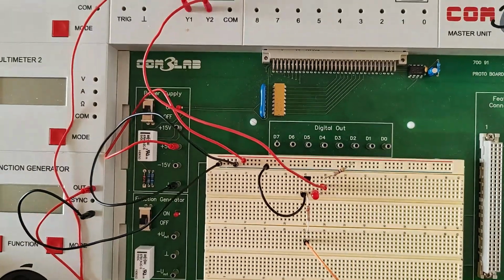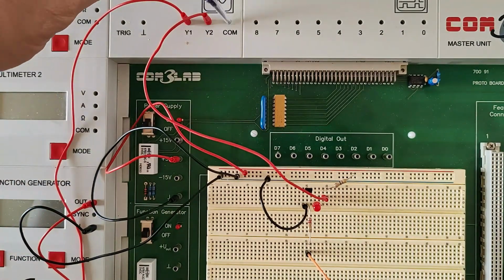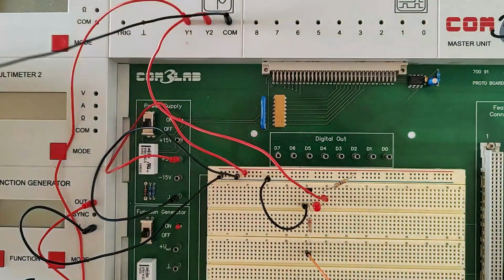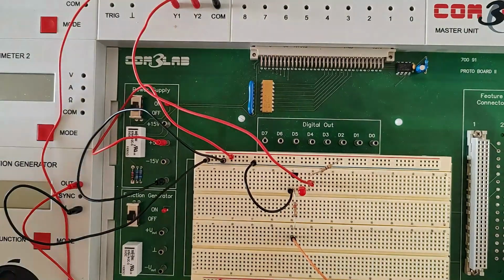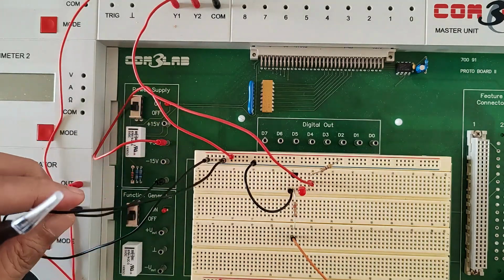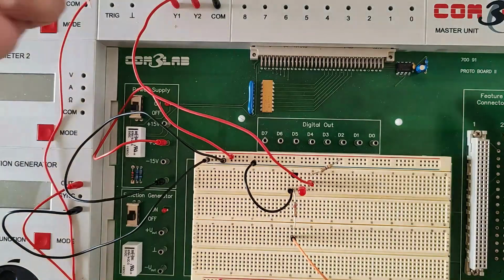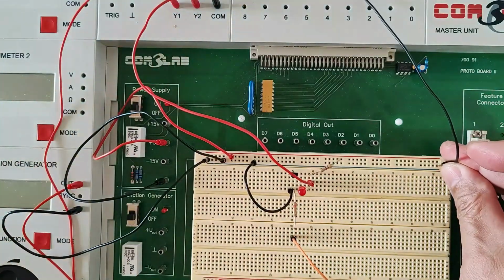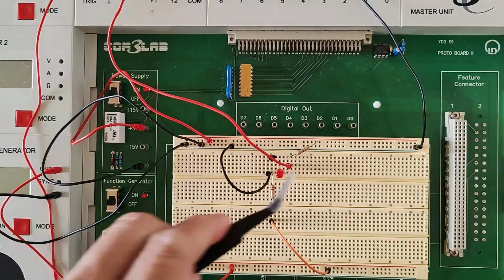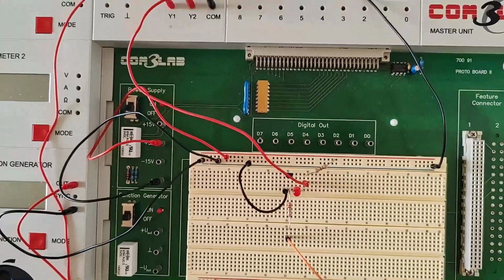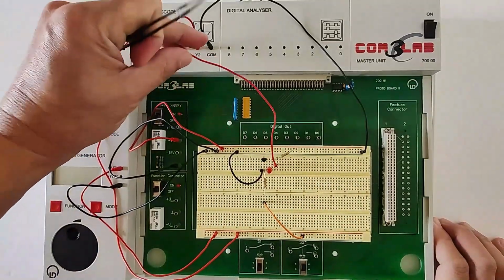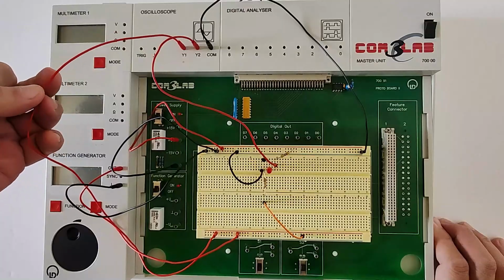Okay, now, the common of our oscilloscope will have to be connected on the same line where the ground of both the function generator, this one, and the 5-volt power source is connected. So let me just connect it there now. Here. Same line. There. That will be the blue side of the top power rail. Once that is completed, our connection is more or less complete with the oscilloscope included.